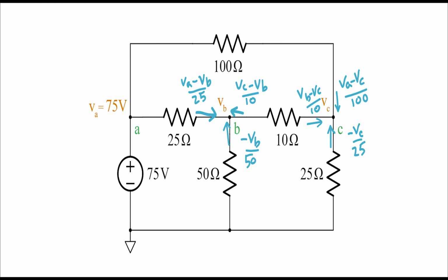The third step of a node voltage analysis problem is to write the Kirchhoff's current laws for each node. When performing a node voltage analysis, you have to make sure that you start from the back of the arrow to the front of the arrow of the currents that you draw. So in this case, we'll draw the arrow from A to B, and as V equals IR, I equals V over R, the equation for I would be VA minus VB divided by 25, and we know VA to be 75, so this equation will be helpful. If your arrow was facing the other way, you would get an equation like VB minus VA divided by 25. You would still be able to solve it, but you just have to pay attention to the direction. So that is how the A to B equation would be drawn in this case.